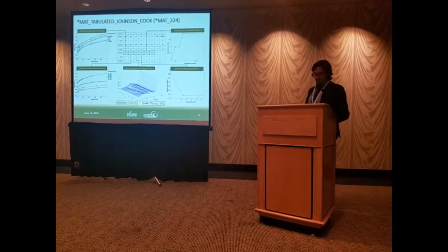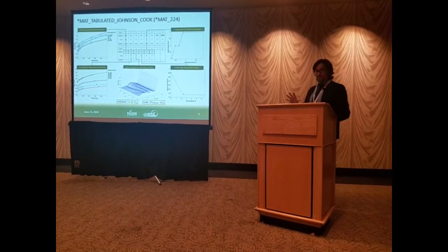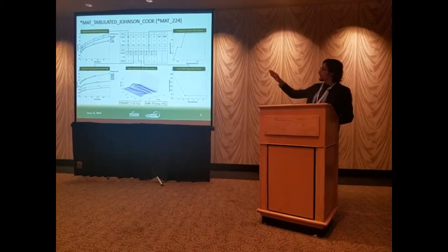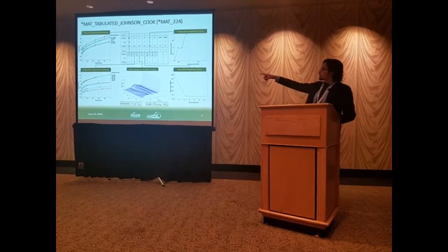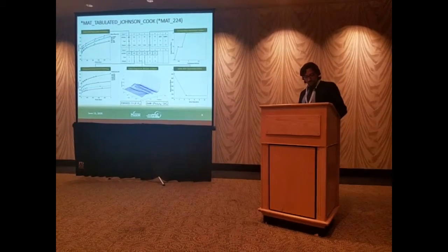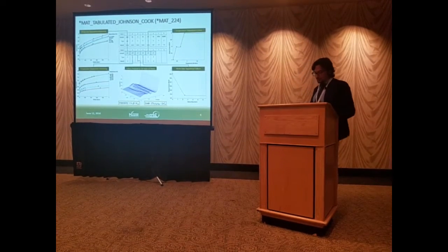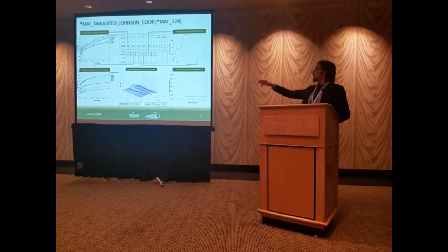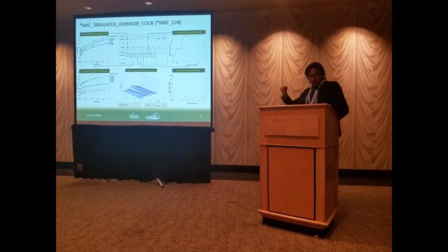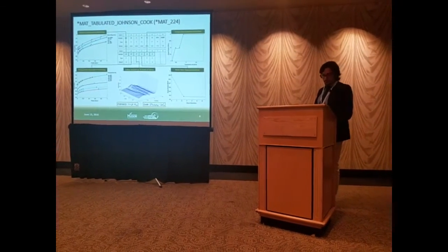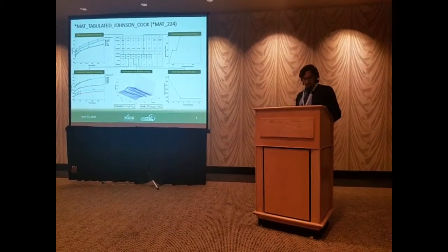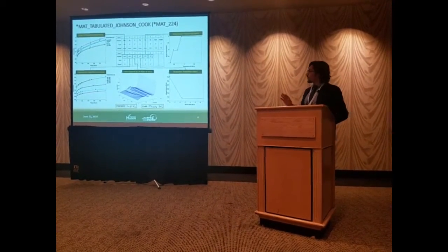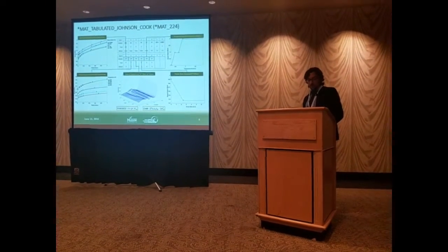LCKT is the temperature sensitive table, and it defines the quasi-static effective stress versus effective plastic strain for that temperature. The third one, LCF, defines for each load parameter a load curve giving the plastic failure strain versus triaxiality. Instead, the last 3 curves define plastic failure strain: LCG as a function of plastic strain rate, LCH as a function of temperature, and the last one, LCI, as a function of element size.